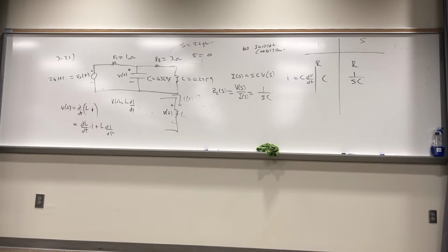Say you have an inductor, and in the center of that coil we have high explosive. What we're going to do is put a whole lot of current through that coil. Now, you know one thing about an inductor. If you try to break the current flow, you'll see an arc across a switch if it's a big inductor. How many know that? It continues because it doesn't want to change the current. It wants to keep that current going. There's almost a momentum to the current with a large inductor.